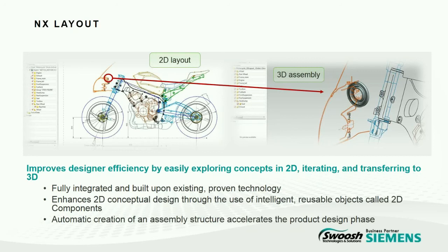And then direct modeling was enhanced in NX6, and they came out with synchronous modeling. Synchronous gives you a lot more capability of editing on the fly without having to completely understand the entire history tree. And then from synchronous modeling, pushing that into the 2D world, we then gained the functionality of synchronous 2D. That, in essence, is the parent functionality of NX layout.